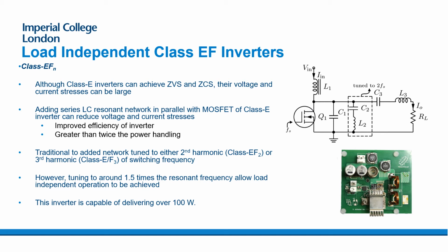And what we've been able to find is that there are a number of solutions where we can actually obtain zero voltage switching for Q1 at both turn on and turn off, even as we change values of RL. So you remember in the previous slide that was not the case. Once we design this system properly with the addition of C2 and L2, we can now get zero voltage switching and therefore low loss, even as RL is changing, and that's really critical for a practical IPT system.